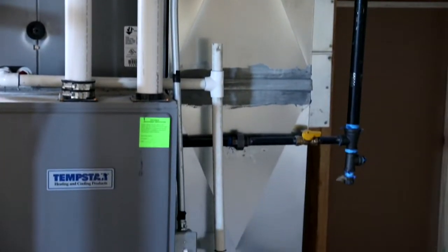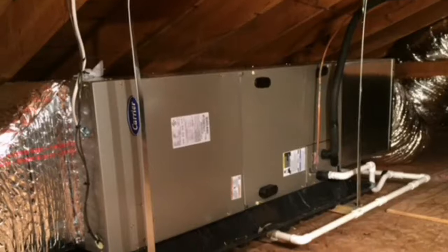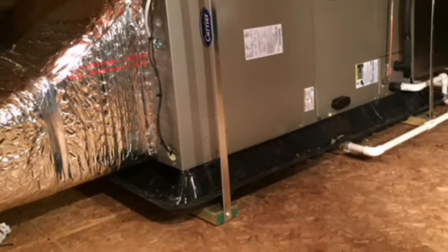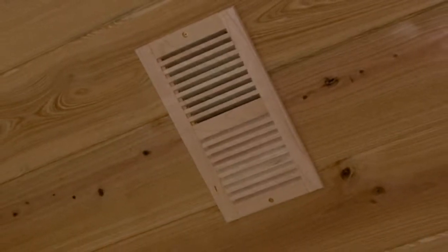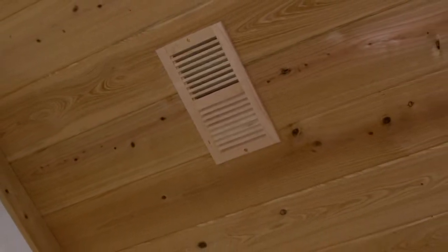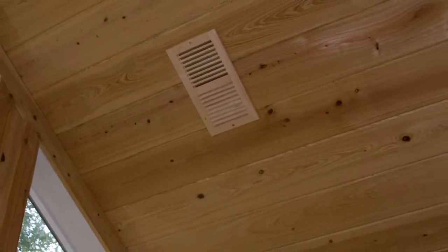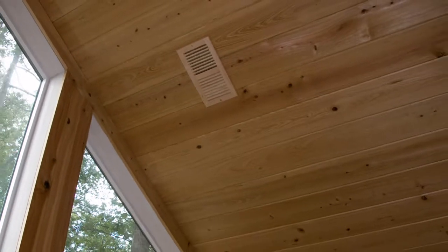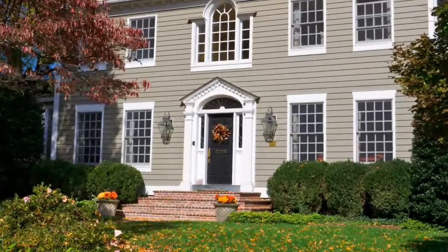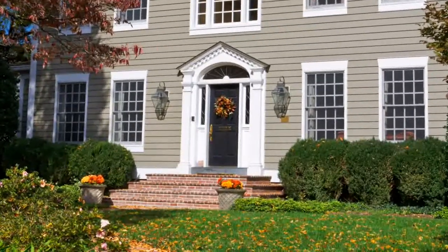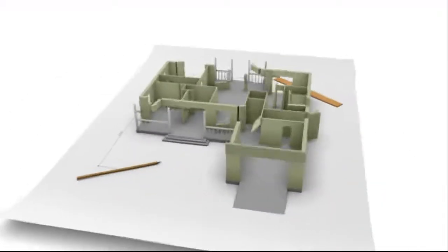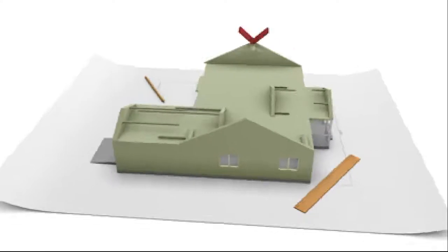The answer is to add a second furnace and AC to the attic with ceiling registers delivering conditioned air to the space. The old floor registers from the basement furnace are permanently closed, and a dedicated thermostat installed on the top floor is used to control the attic furnace serving just the top floor. This home would then have two separate zones independently controlled using two separate thermostats. For new construction, a broad selection of zoning options are available, and they're also the easiest and least expensive to install.